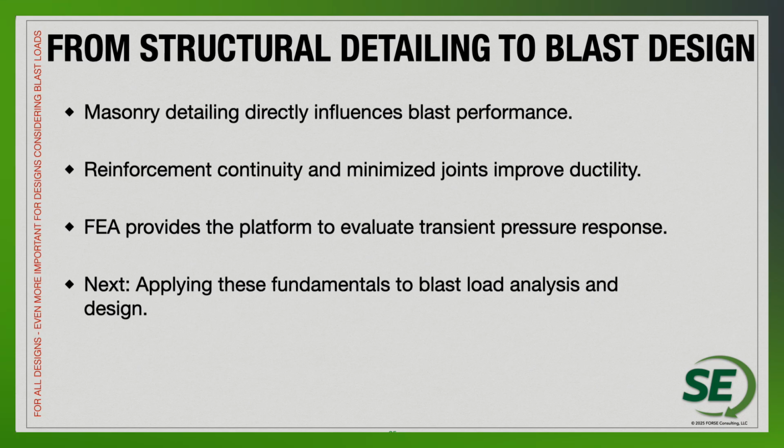So again, from structural detailing to blast design, we're really looking at the masonry detailing, how it's going to affect the overall performance of the masonry wall, and how that masonry wall is going to be well suited to handle the different high demand loads that you would have from a blast event. Looking at reinforcement continuity, minimizing some of those joints to improve ductility, and looking at, if we do have openings, how the different finite element analyses can be utilized to understand different stresses and forces as they move around some of those elements.